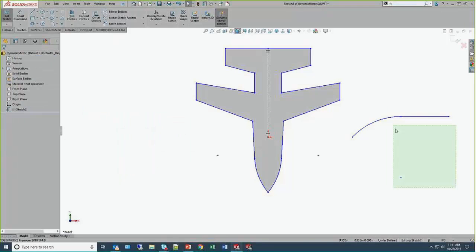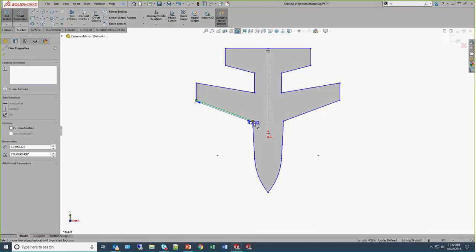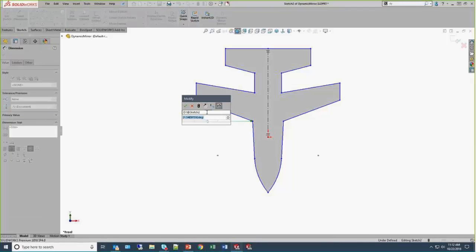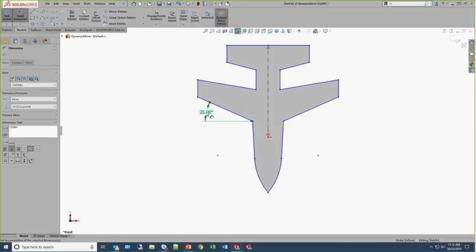Now I'll use a couple of crossing windows here since I really don't need that additional information. So that dimension for the sweep back of the wings, how do we create that without adding anything else? Well, that's just a regular dimension, and we'll select the line at an angle and then the point. And then we have this cross with these axes, and we can specify 2 different horizontal datums for the dimension, or 2 vertical. This is something that SOLIDWORKS added a couple of releases ago, and it's really convenient for adding these angular dimensions without needing all that extra construction geometry. So another little simple tip on the side there.